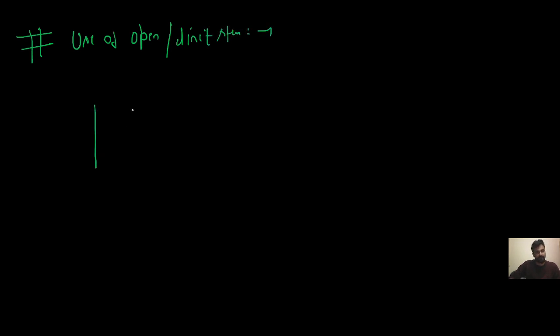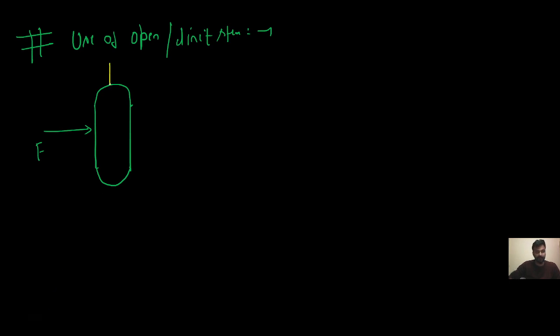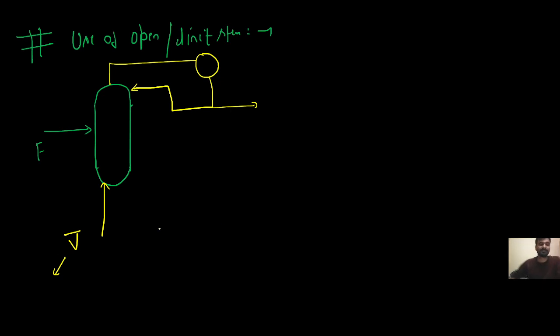So basically, whenever we want to distill any product from a continuous distillation column, feed will be entering, and the heating medium used to be a heater, right? But here we are not using a heater in the open steam distillation column. Instead of a heater, the use of direct steam is recommended here. I am assuming V bar is the molar flow rate or mass flow rate, whichever the problem uses. That V bar is equal to the steam flow rate.